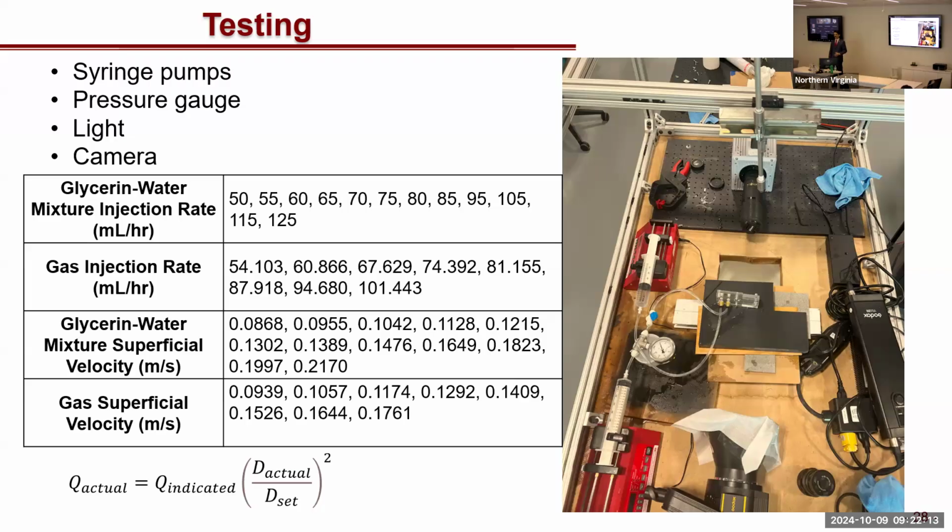And so it was also of interest to us to know what the mass flow rate of the gas is. Since pressure isn't constant, and there's a pressure drop across the 2-phase flow region, and the outlet is atmospheric, there's going to be a high pressure at the inlet. So we want to know what the mass flow rate is. In order to determine the mass flow rate, we needed to know the pressure.